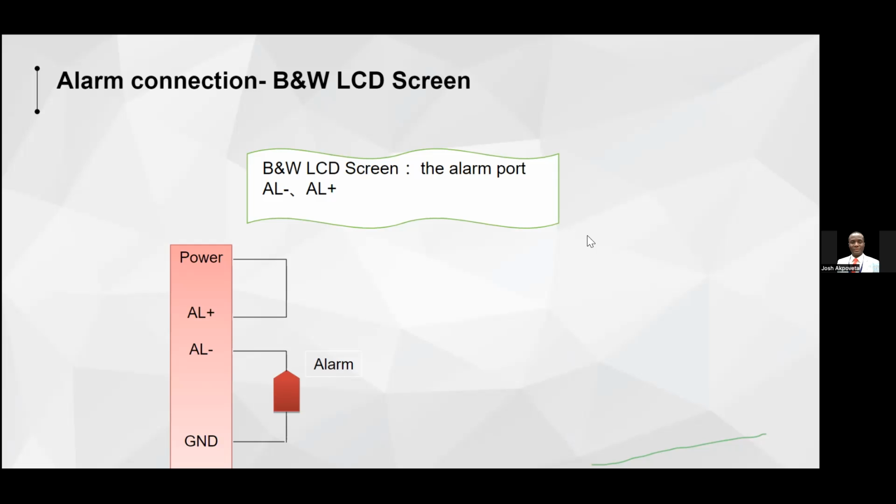You need to check, is the card actually the right model of card that should be used on that device? Because sometimes some people will use a MiFare card for an RFID device and they expect it to work, not understanding that they are using two different kinds of frequency of readers, right? So if you're not seeing the user that you registered on a device, it means it has not been registered.